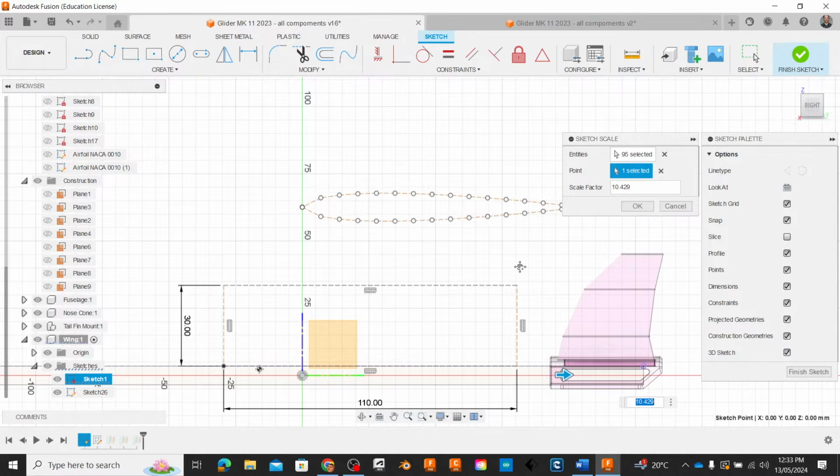I just made one tiny little mistake there. That's all right. I'm going to take this profile here, extrude it out, and then I'm going to actually loft between here and here. So loft, profile, profile, really nice and smooth. The reason this works so well is because I've used the same sketch profile consistently copied out the whole way.